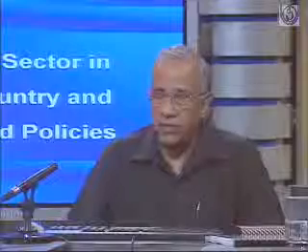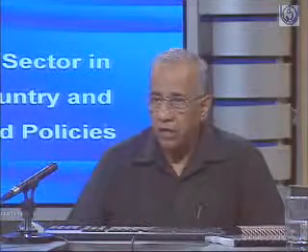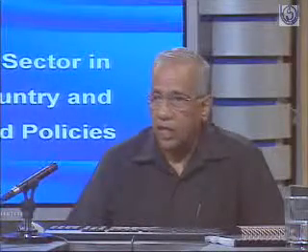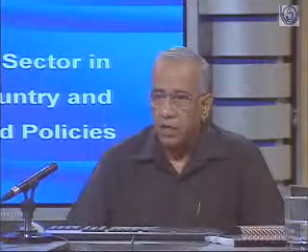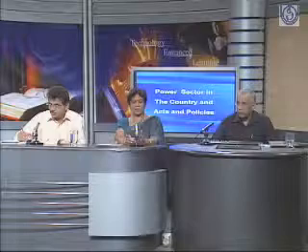Let me explain. The frequency of operation in a thermal power plant has something to do with the rotation. Once you come back to the power generating unit, 50 hertz of frequency would mean 3000 RPM of a thermal machine, rotations per minute. 3000 revolutions per minute, and 60 hertz would mean, Anjali, how much? 60 hertz would mean accordingly.